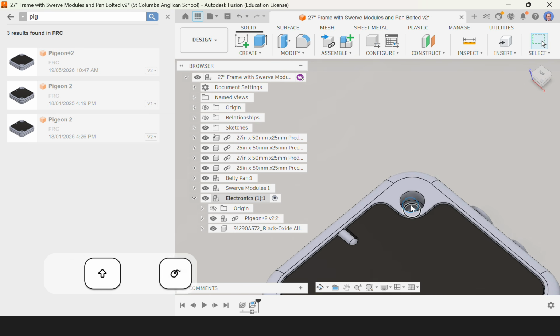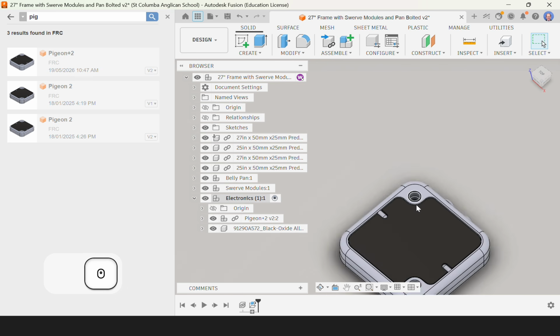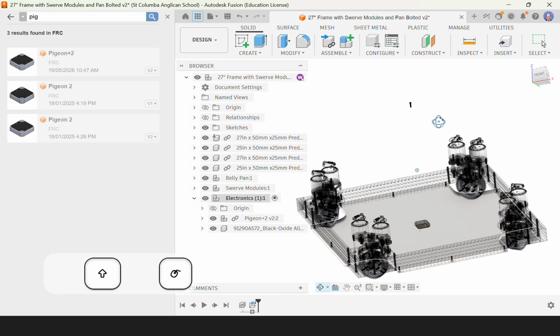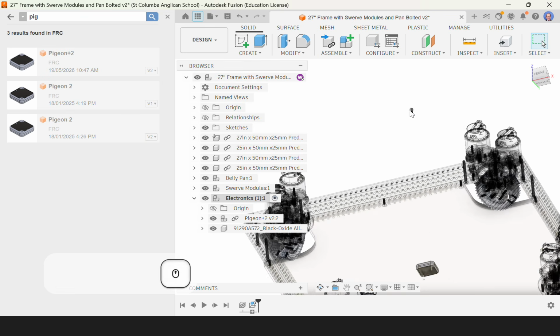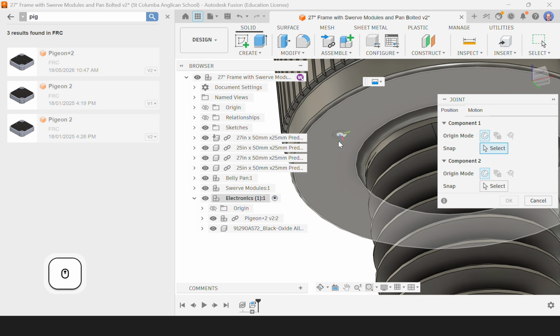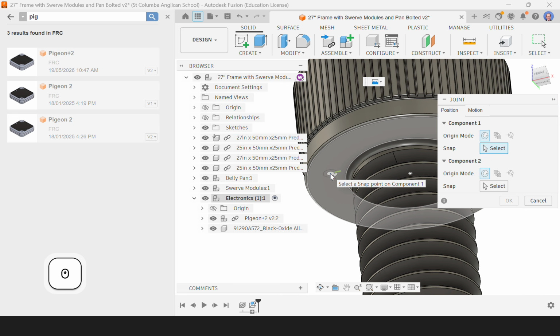face down in there. Right, so zoom out where I can see that screw, pull the view around so I'm looking at the bottom of it, zoom in there. J for joint. Hover over the face that I'm interested in that contains my joint origin. Hold Control or Command on a Mac. That locks that there so that it doesn't disappear.